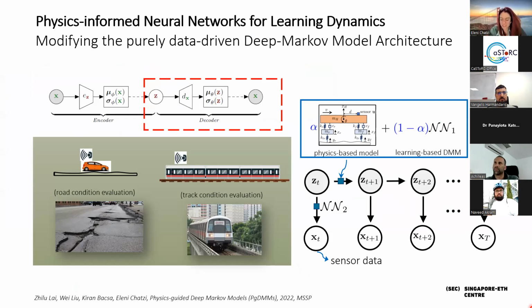This is usually the case for systems like bridges, for example, when they're operating under normal, regular, and expected loads. The issue is if you have, for example, an earthquake, or a phenomenon that excites geometric nonlinearity. When things start becoming a bit more nonlinear, it's not guaranteed that we have a very good approximation of the nonlinearity that is taking place. And what's even worse, usually, is accounting for the actual damping that is in place, because our assumption on damping, which is usually a Rayleigh type of assumption, is a convention. It's not guaranteed to actually reflect what's going on in reality. So in those cases, we usually have some sort of term that could be missing from what we suspect from the actual model. And that's where we found it useful to include such a term that is learned.